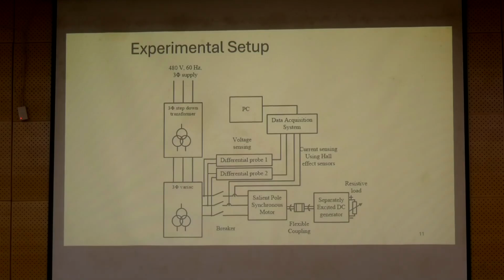So this is just because my lab power supplies were not matching. So I had to do this arrangement. Otherwise, if you had a power supply that matches the machine's rating, then you just need a variac to control the startup transients. And if you are doing an inverter, you can easily implement startup transient control in the inverter itself. But most of us would prefer to use a variac because it gives you an extra layer of protection.